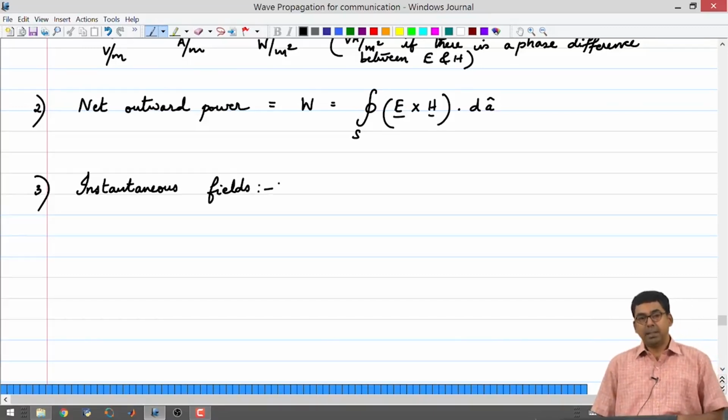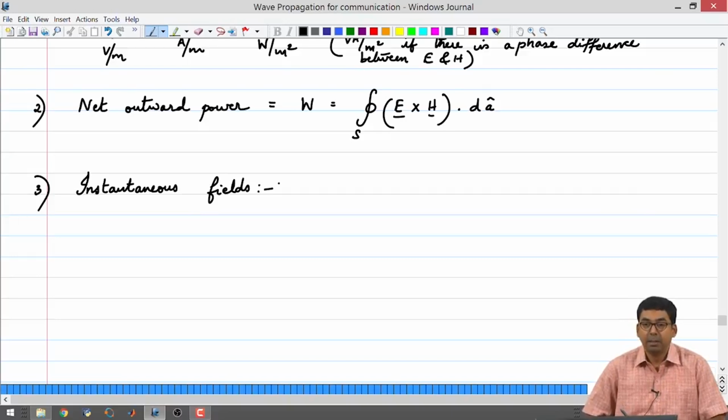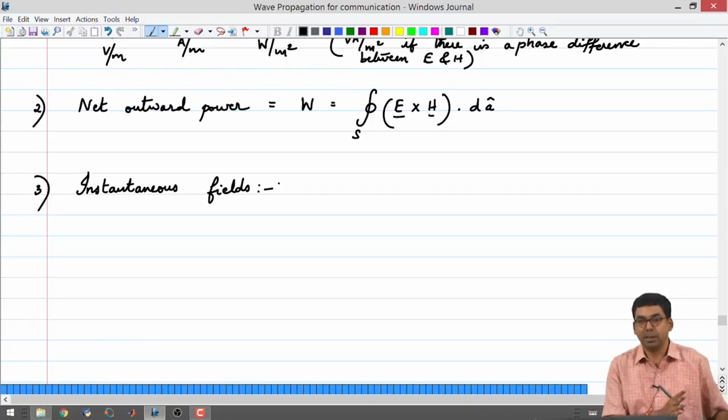By instantaneous, I mean that I will be using e to the j omega t for describing both the electric and the magnetic field. It has the effect of time. So, I am using e to the j omega t to describe electric and magnetic fields as we had seen before, in the beginning when we had started with AC electromagnetic fields. We had included the periodicity with respect to time to be an exponential, and then we will take the real part of this exponential.